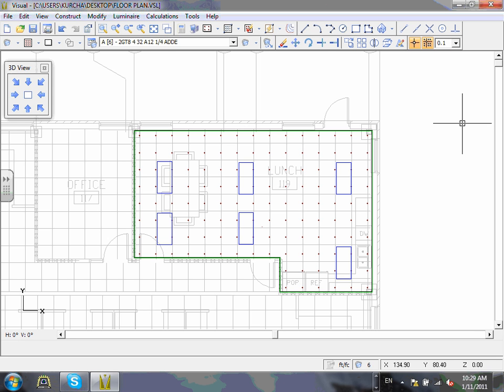I put 6 fixtures. Again, that probably would be overkill. How did I place them? Based on looking around. You remember how we did the criteria for placing and so forth? Here's one criterion. Usually you want to move, guys, at least 2 feet off the wall when you start placing them, and I placed them. I think this should give me a good calculation.